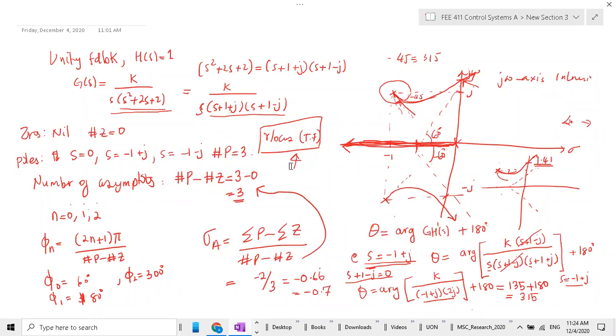And the beauty of root locus is that once you have your root locus in proper dimension, as a scaled root locus, then we can use frequency response specifications and time domain specifications to get parameters.